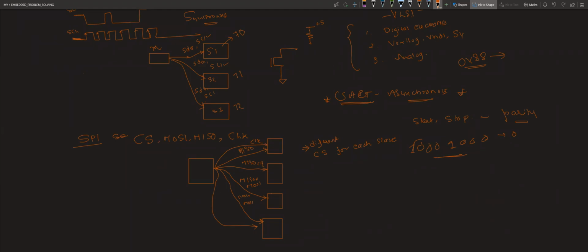So for long distances, we have this error correction or error detection mechanism, right? For very long distance UART is preferred, and you need not transmit the clock also. Whenever you transmit the clock, there is always a possibility of emission, interference, all these things. So it is preferred. Okay, we will launch some polls.